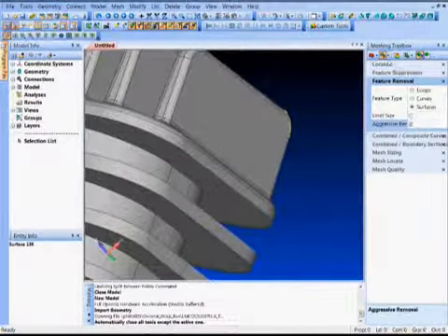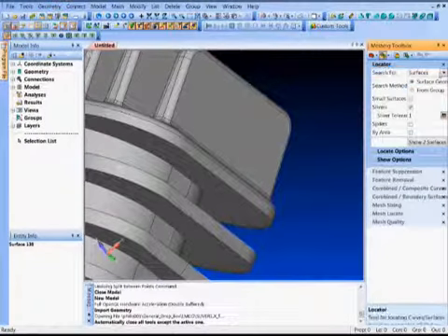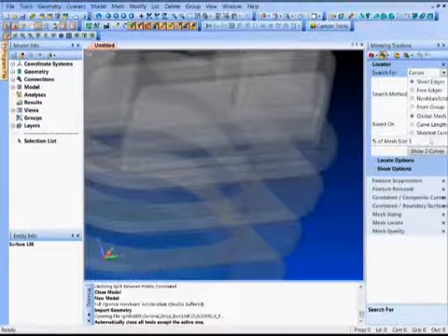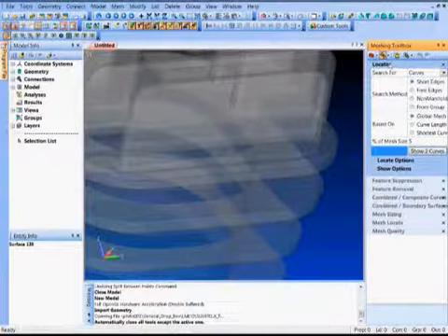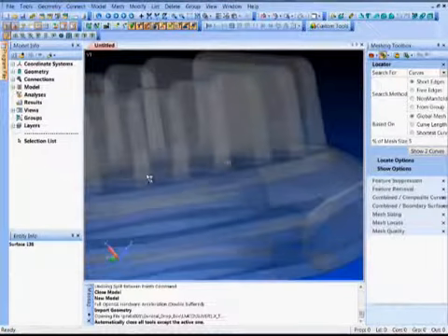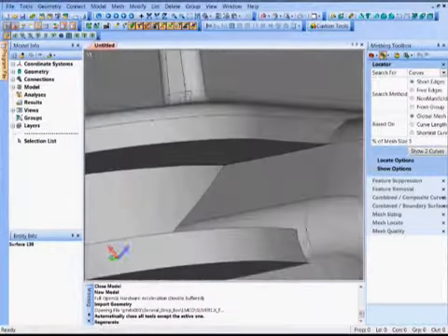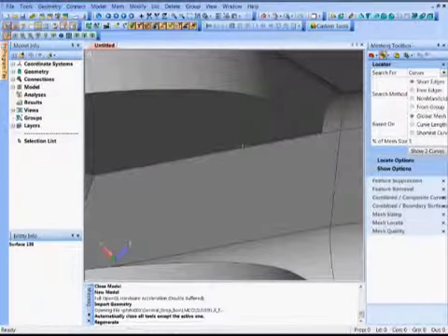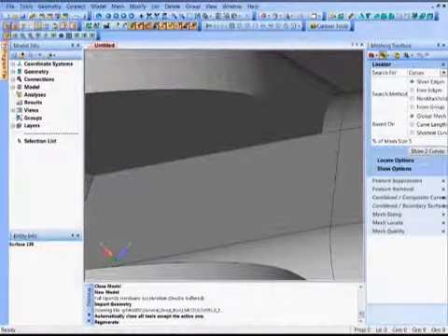Let's make sure we don't have any short edges in the model. So go back to the locator, go to curves, and let's see what we got here. There are 2 curves that are pretty short, and let's see where these are. It zooms in. Oh, looks like we got another little ledge in here, this little flag-shaped surface.